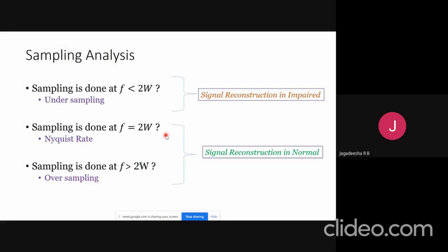So if you collect 2 samples, maybe one in the positive half, another in the negative half, then you can represent a sine wave, right? One on the positive side, one on the negative side. That satisfies this condition. You have one sine wave, just one frequency, one positive half, negative half. That is one cycle. So you collect 2 samples from it. Yes, you can almost represent a sine wave, right? Or if you collect more samples from it, of course, you can easily represent it.